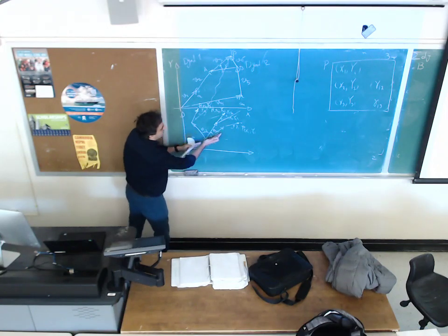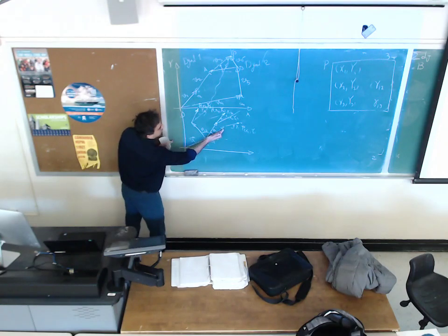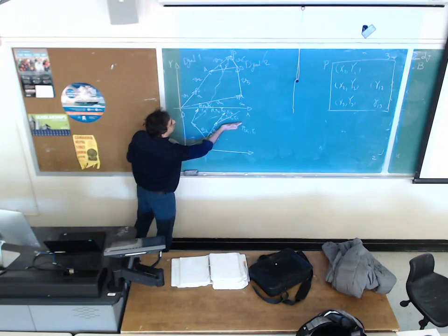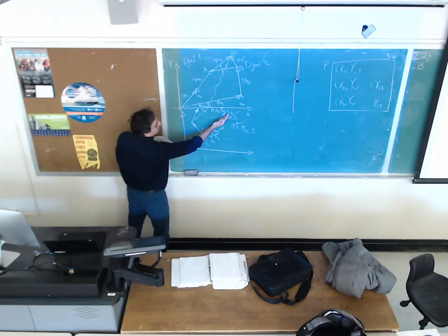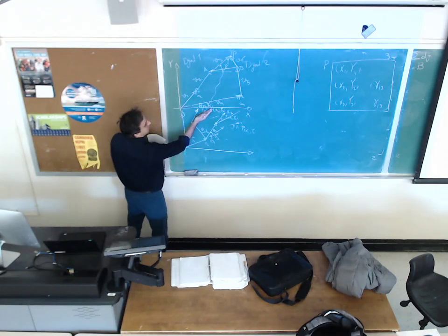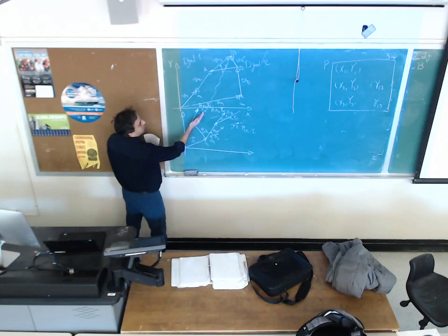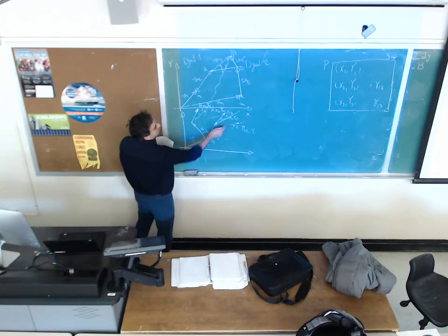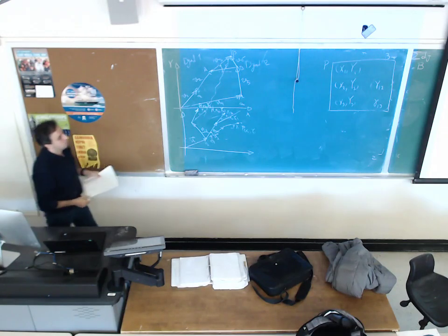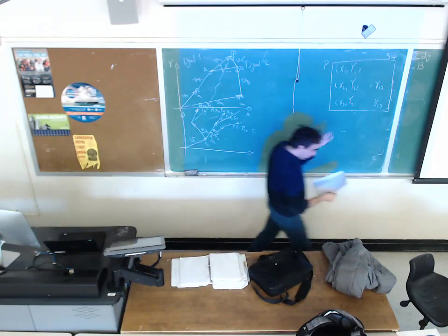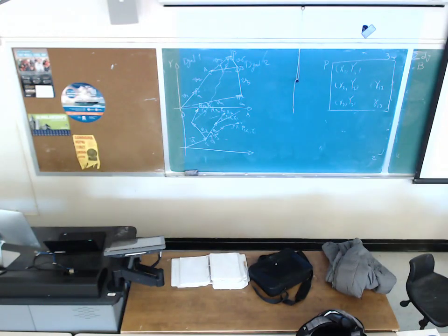So when vector V2 is moving from the first precision point to the second precision point, the vector V3 is moving from this location to this location by the angle of gamma 1,2. And when it's rotating by theta 1,3, this guy is going to rotate by the angle of gamma 1,3 from the first precision point orientation. So this is what you can see on the first diagram.